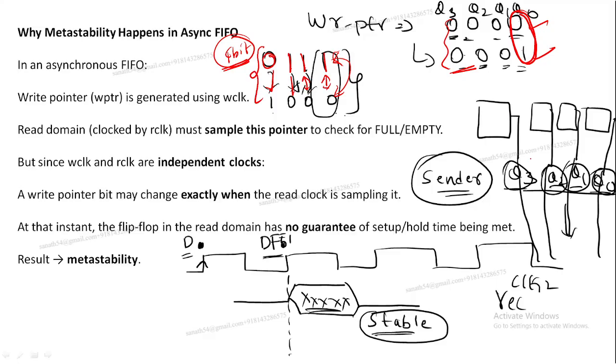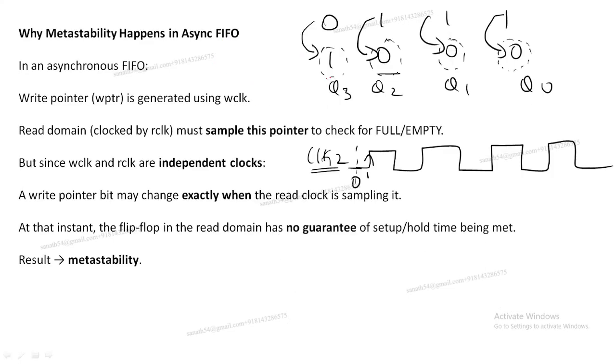Normally the counter outputs are the flip flop outputs, q3 q2 q1 q0, so these 4 transitions we can't recommend. That's why binary counters are not recommended, and we go for gray code.